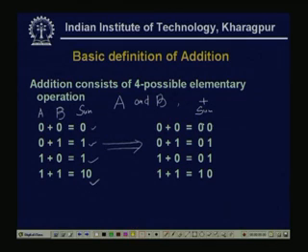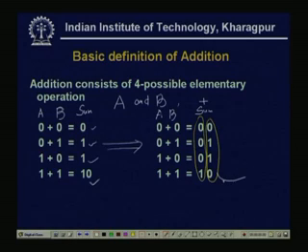Say there are 2 bits, this one is the LSB and this is the MSB. If I add A and B, and my sum is realized by only 1 bit, the lowest bit, that means 0 1 1 0, I can define as my sum bit, normally denoted as S. And this 0 0 0 1 we call the carry bits, normally denoted by C.